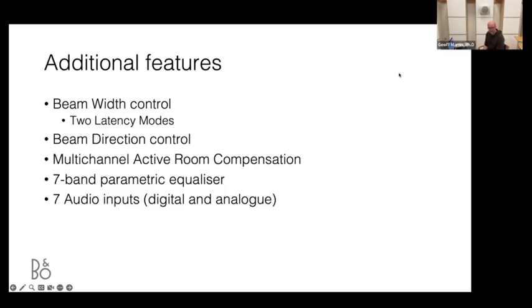When they get installed, the customer or the installer will plug in a microphone that can be attached to the back of the speaker. And it runs a sine sweep on each individual driver, and then calculates what the response of the speaker will be in each of the directivity modes that I just explained.